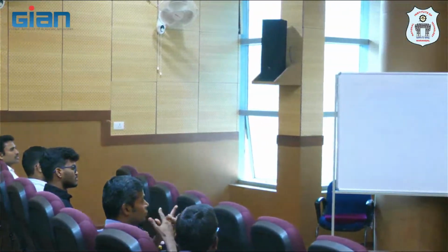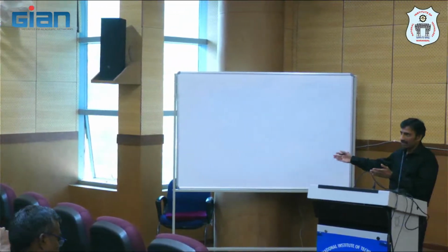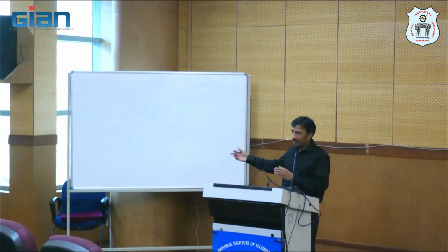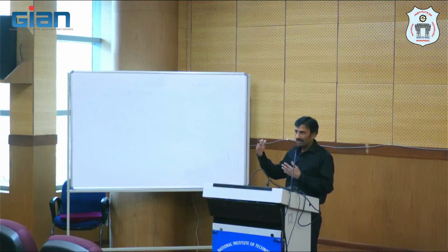Okay, so is the general idea clear? I'm going to start with raw data. We do some data processing and generate features. The feature can be multiple quantities. It need not be one quantity. It need not be just RMS, mean, peak, kurtosis, like that. So then the feature becomes a vector. I get a label. I stack feature vectors and labels one below another, and I get my training data set.